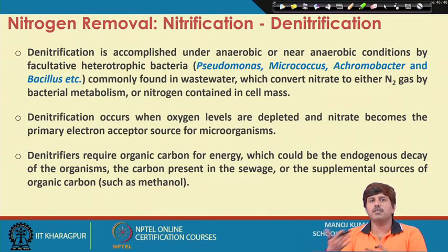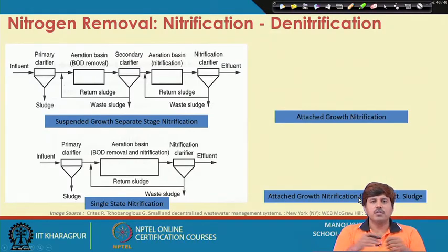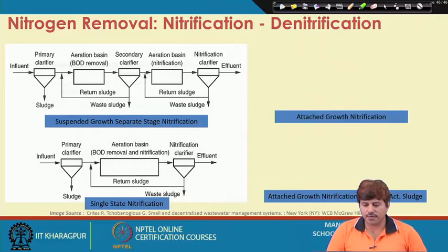If not, a supplemental source of organic carbon like methanol or acetate can be added for the organic carbon requirements of these anaerobes.